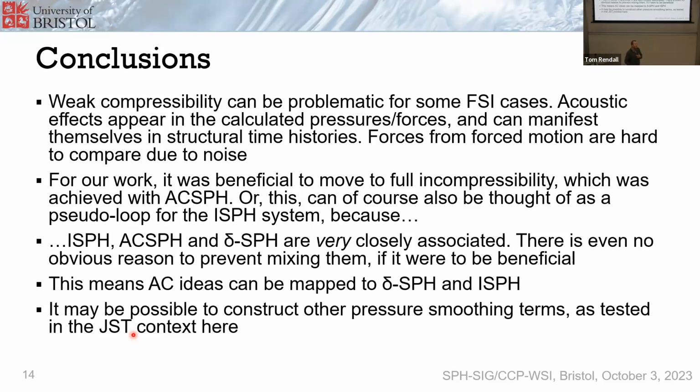So, in some of the other work on artificial compressibility, you need to define an effective wave speed of the pseudo time equations. Because in the pseudo time, you're not compressible, you have propagation of information like the whole artificial speed. And then you can choose schemes like weakly compressible, with a speed 10 times the max velocity.